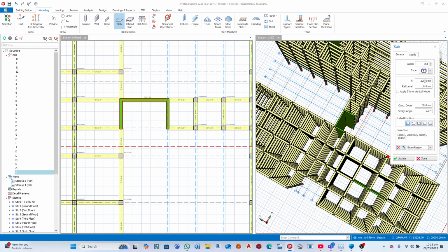King Salman was what? Wasn't that 375? What was the depth of those slabs? 275, huh? Let's do 250 mm. Loads, let's treat it like a balcony. And then let's use 2.5 of imposed load. Okay.